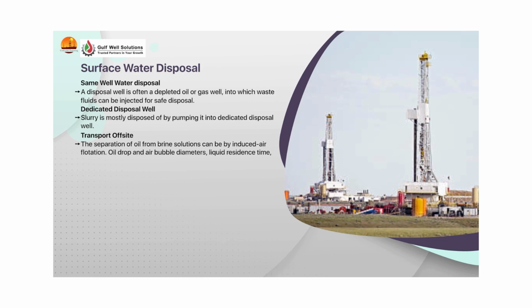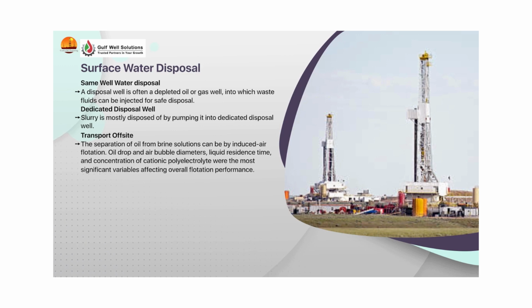The separation of oil from brine solutions can be by induced air flotation. Oil drop and air bubble diameters, liquid residence time, and concentration of cationic polyelectrolyte were the most significant variables affecting overall flotation performance. Wellbore separation.